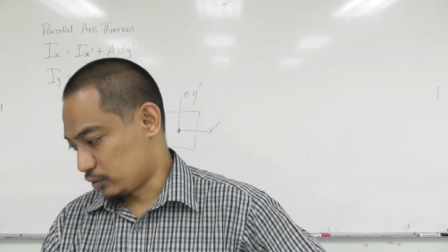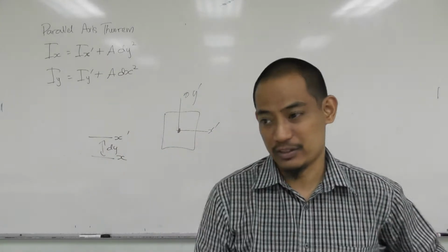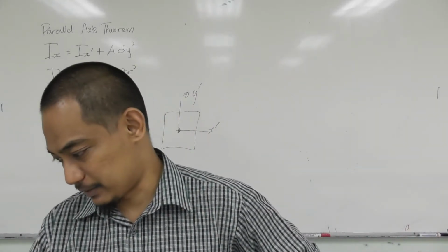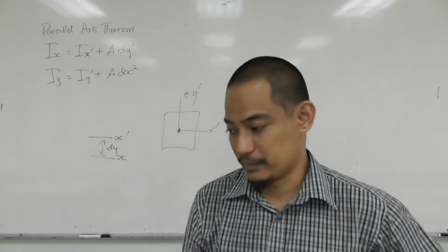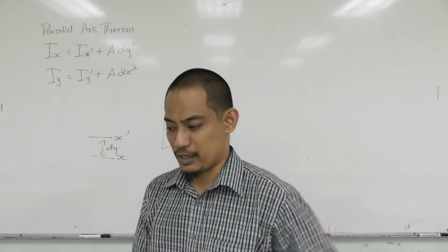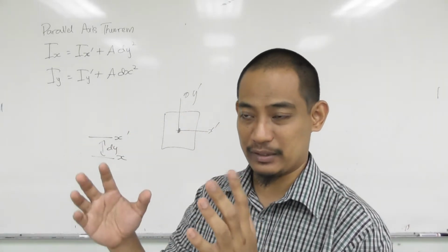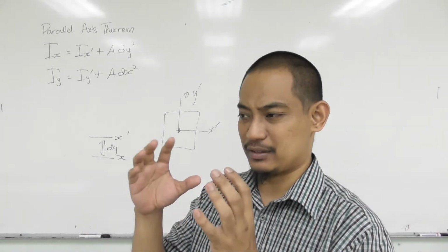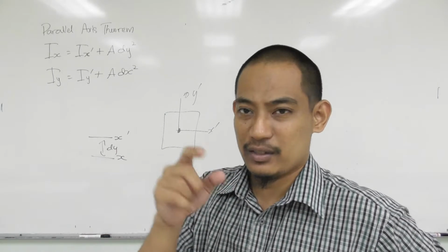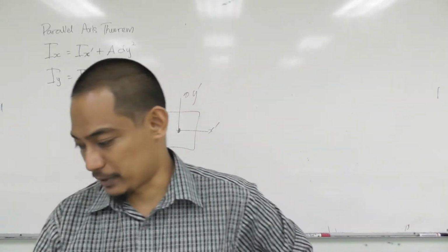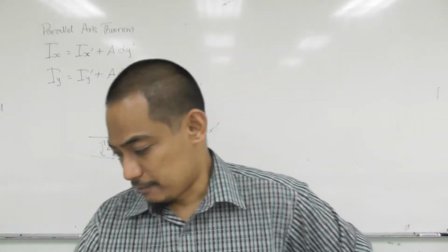Right? So radius of gyration we totally skip. Now, moment of inertia for a composite area. The steps are simple. Step one: if you have any particular shape, you divide it into some basic shapes, right? And some divisions can be additions or subtractions. If you have a hole, you subtract that area. That's number one, and we will go into the example. It should be clear after this.